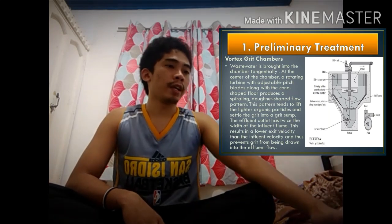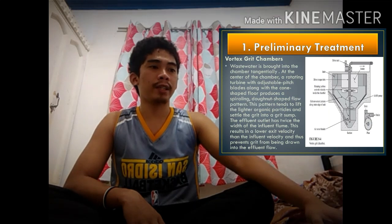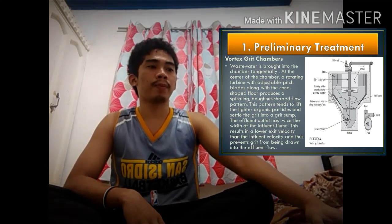The second type of grit chamber is the vortex grit chamber. Wastewater is brought into the chamber tangentially. At the center of the chamber, a rotating turbine with adjustable pitch blades along with the cone-shaped floor produces a spiraling donut-shaped flow pattern. This pattern tends to lift the lighter organic particles and settle the grit into a grit sump. The effluent outlet has twice the width of the influent flume. This results in a lower exit velocity than the influent velocity, thus preventing grit from being drawn into the effluent flow.